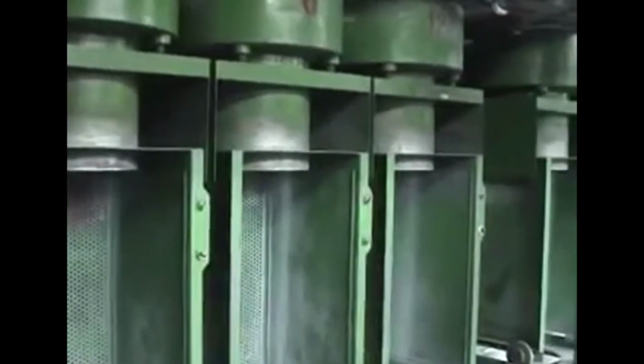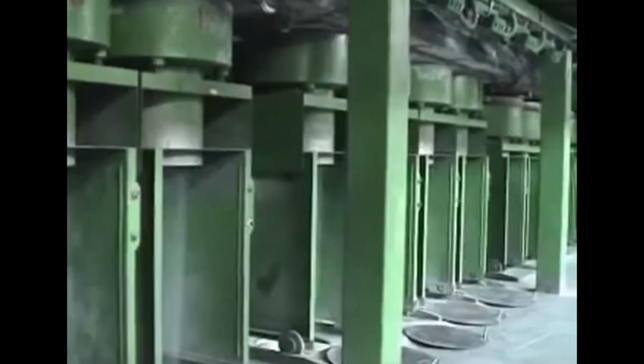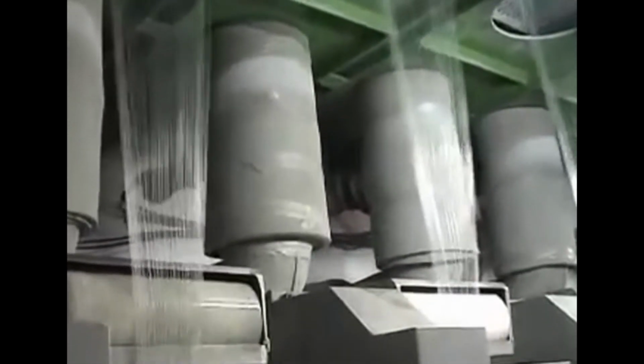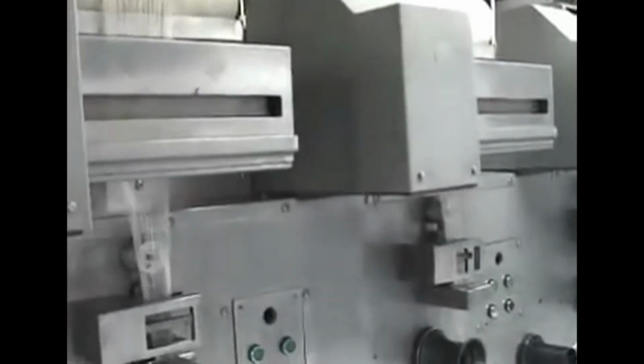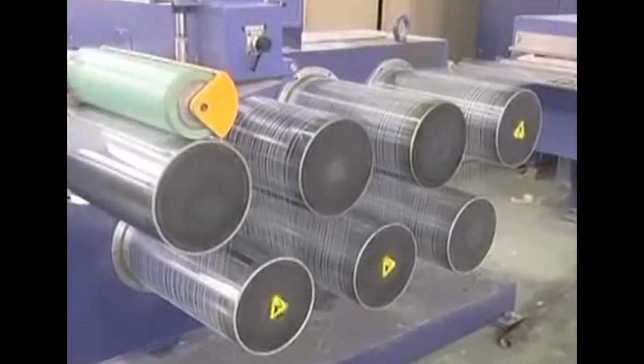So, from the holes of the spinneret, it comes out in thin form and it becomes a filament. It gets solidified by hitting the air. And when you check the particular filament, it will not contain alignment of the molecular chains within it. These molecular chains need to be aligned to the fiber axis in order to make it stronger.